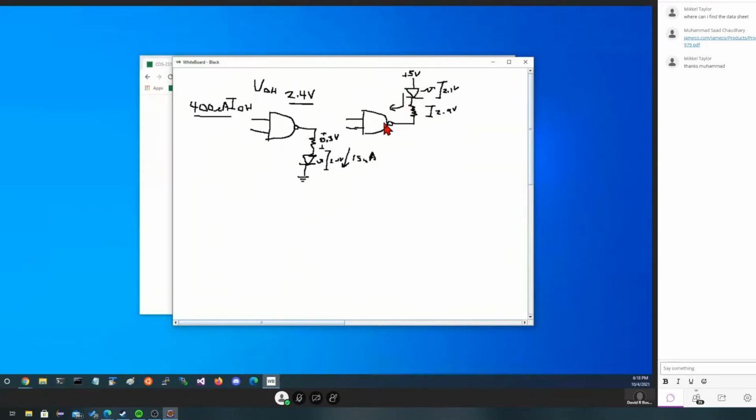When we ground this, which is when this would be turned on, what value is V output low? Scott? It's 0.4 volts maximum. Okay. So if this can go down to 400 millivolts here, then we still are going to get a drop. It's just not going to be 2.9, right? We're just going to take 0.4 off of this.